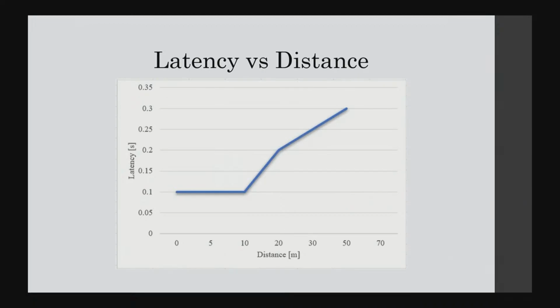We use 2 XBs to communicate with each other. The received signal was shown on an oscilloscope. By recording the signal with a stopwatch, we record the time. All the times were subtracted by 0.5, which is the human reaction time. The maximum communication range we achieved is 50 meters. After 50 meters, there is no communication.